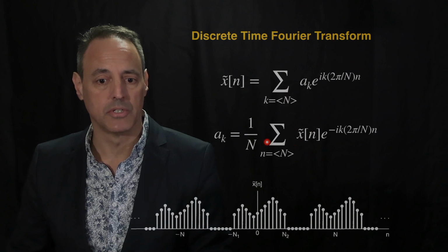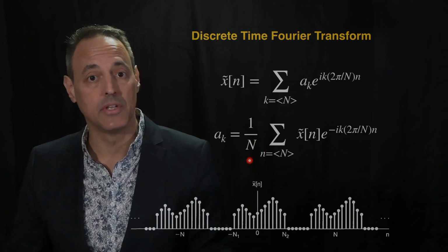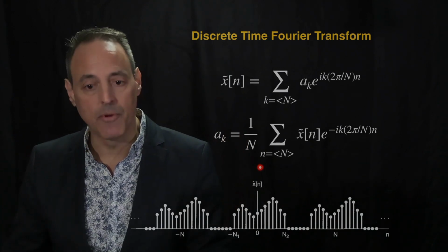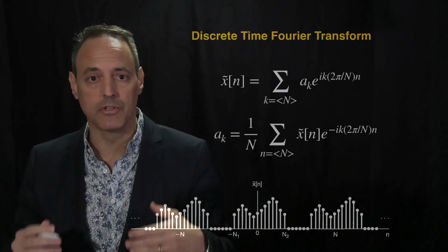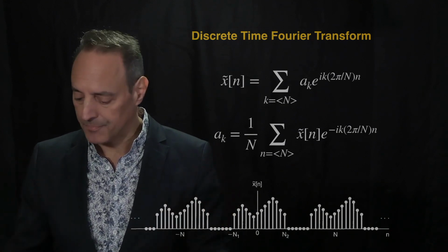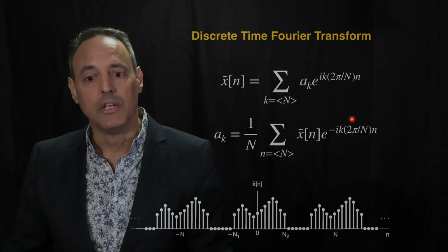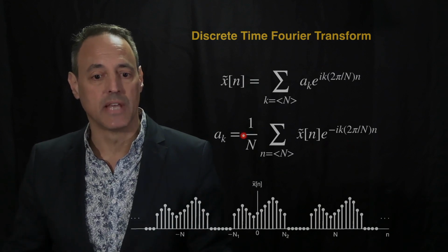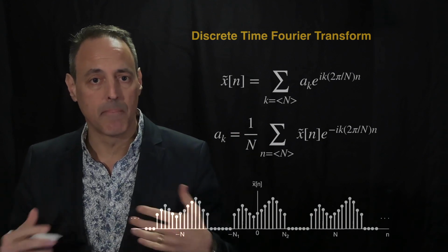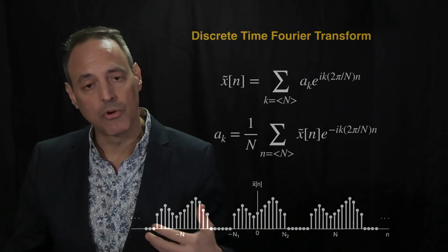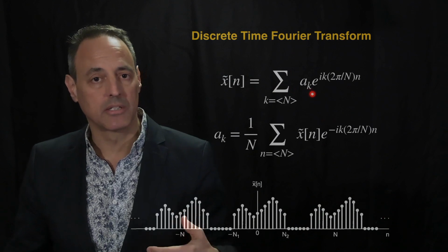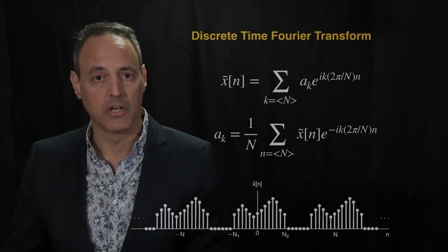Here is this representation. It's 1 over n, where n is the period of this discrete signal. And you're going to sum over a total of n points. And usually you just pick the easiest and most convenient n points to make this period. And you take this signal, you project it onto the Fourier modes, and this is how you can compute the a of k. So this is the idea, the summation over the Fourier modes and computing these coefficients, which allows you then to estimate or approximate this signal in a Fourier decomposition.